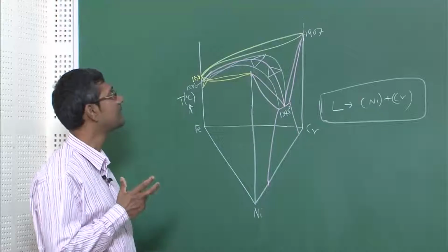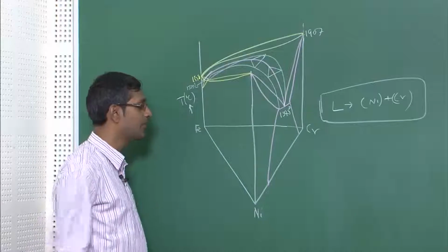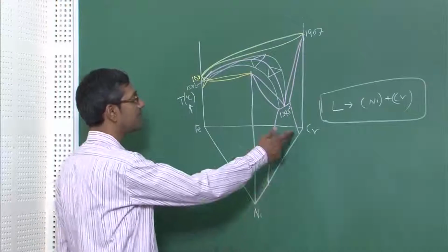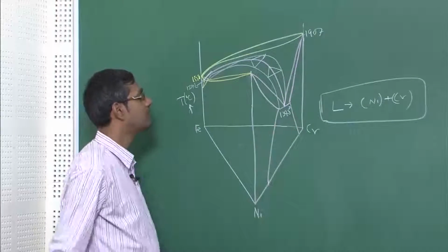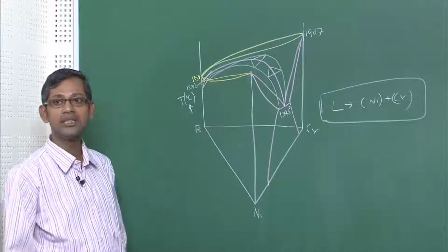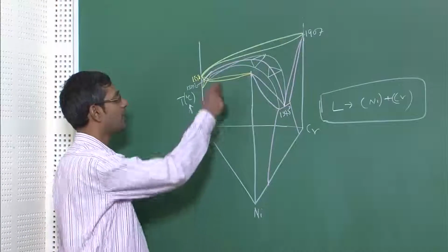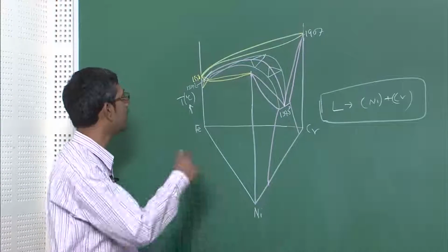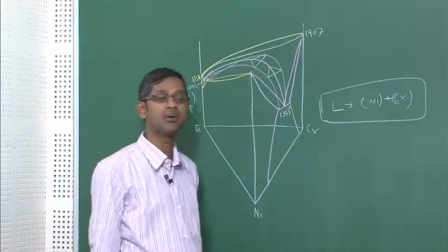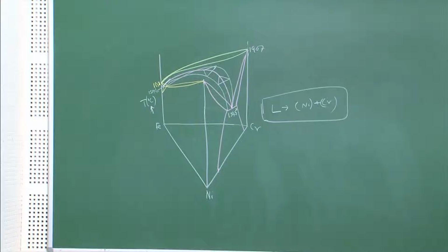Otherwise this phase diagram is very simple, but on the other hand, if I take alloys which are chromium rich, on this side, they are very easy to handle, but normally God does not give the easiest thing in the world. So, that is why most of the alloys which are stainless steel type will be undergoing the peritectic reaction, and that is the problem. So, I guess it is very clear from the binary phase diagrams what is going to happen.